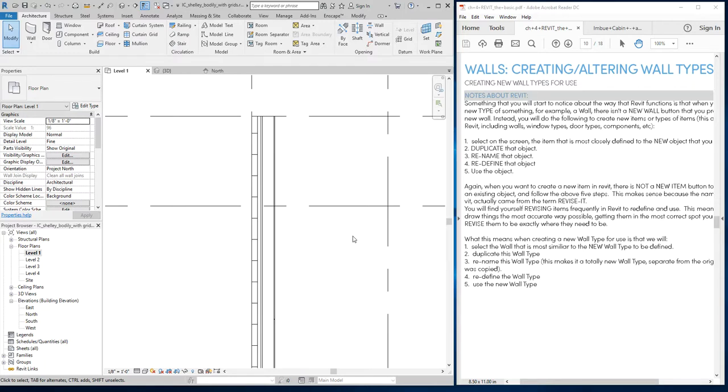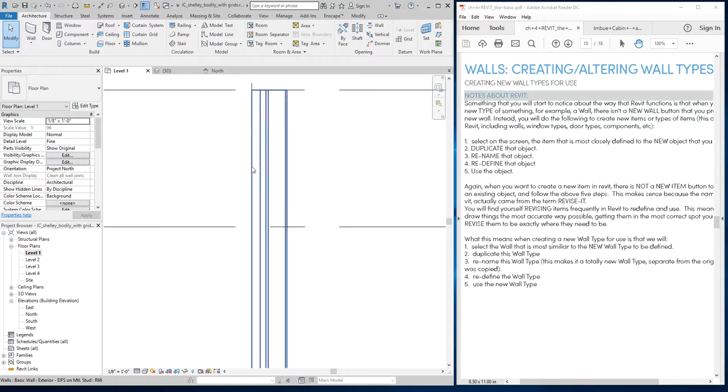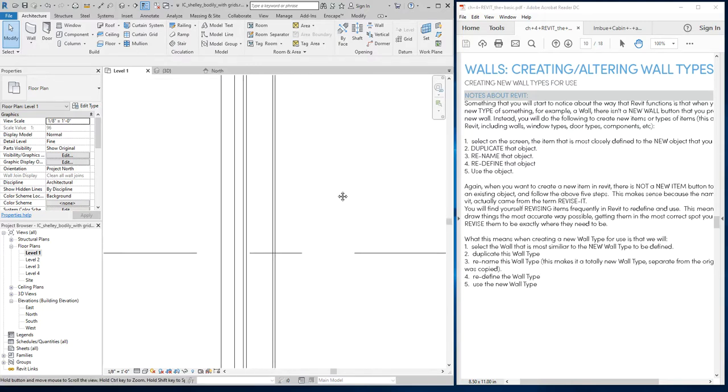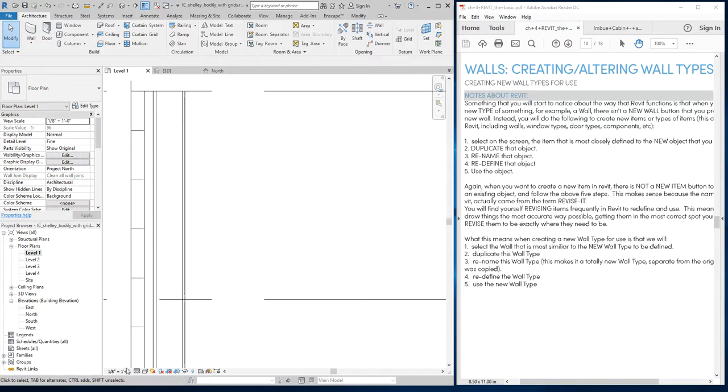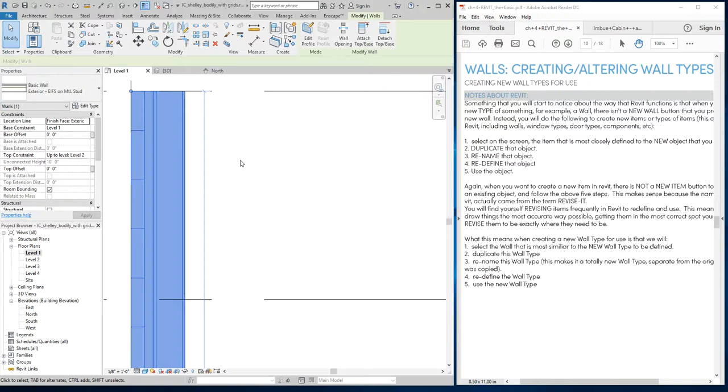So what I just did there, right, I changed the coarseness level, and it took it from a fundamental outline block, right, to a well-defined layered wall system. So here, I can see all the different layers of my wall assembly. If I click on shaded view here, I can see them in color, right, which is kind of nice to be able to differentiate them. All right, now let's look at the actual wall assembly of this. So to view the wall assembly, I'm going to click on my wall. I'm going to come over here and click on Edit Type,